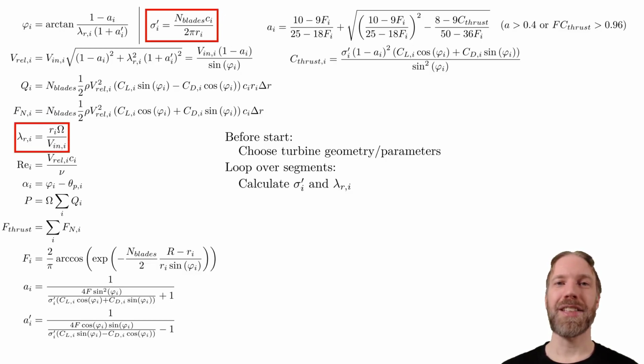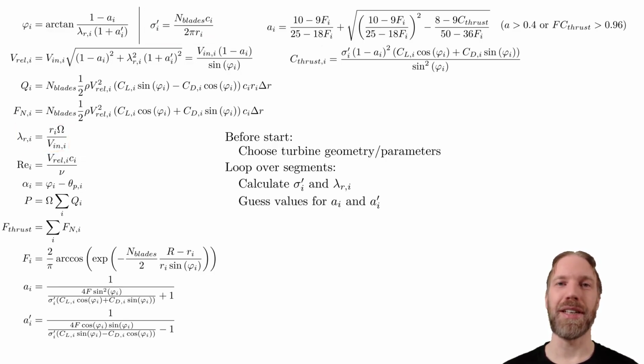The induction factors will have to be solved numerically, as we cannot expect any analytical solution, especially due to the evaluation of the lift and drag coefficients. Therefore, start by making initial guesses for these. An example of a starting guess could be the optimal values for the factors, or if we previously solved a similar turbine, that solution could be used as an initial guess.